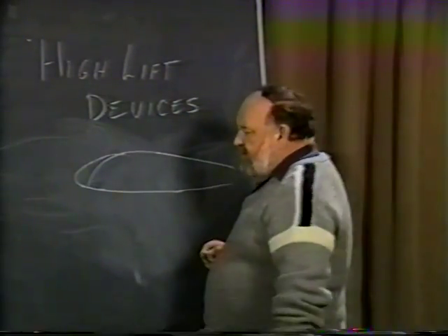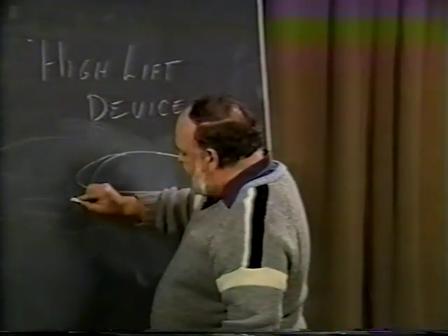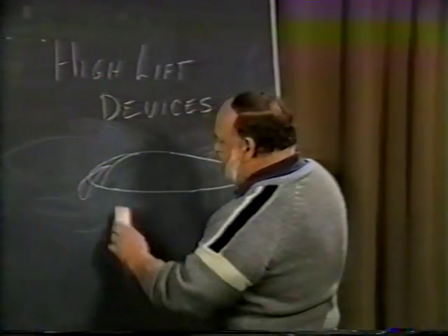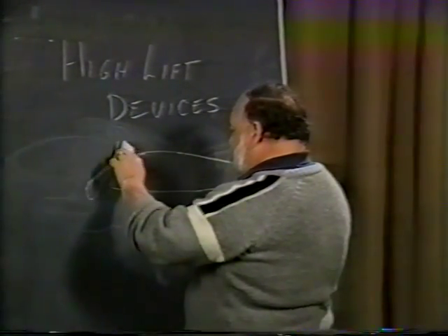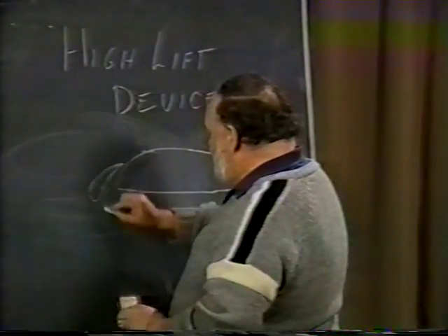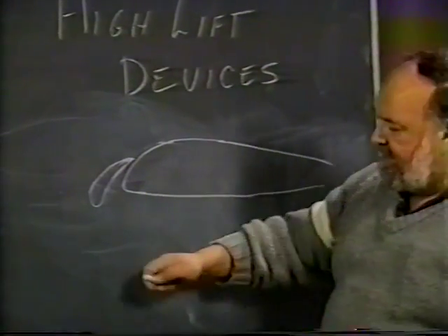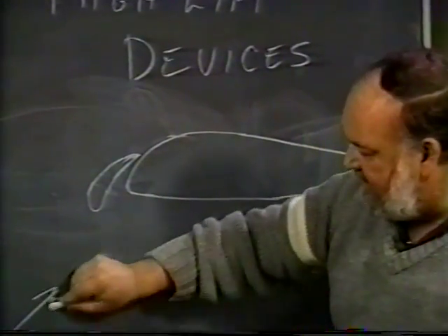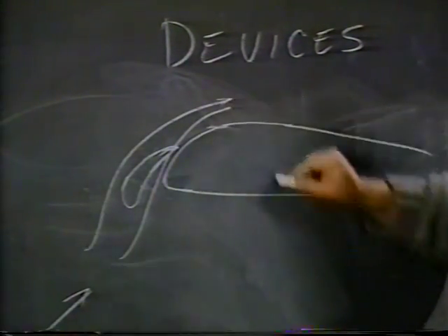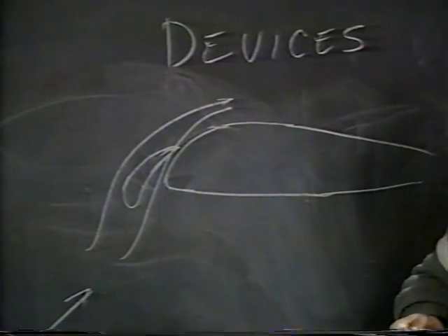adjustable leading edge slot whereby the surface moves out on a track similar to that. Now you can see that you have just about the same advantage as you get to high angle of attack. As the air is flowing in this direction, it will then be vectored through this slot and up over the top of the wing, preventing the leading edge from stalling to a much, much higher angle of attack.